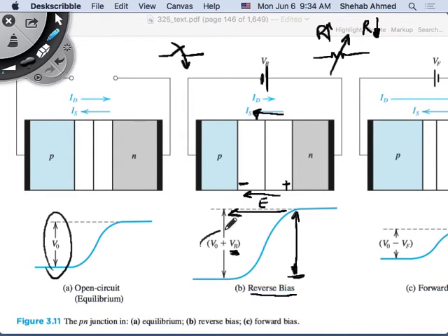Physically, what's happening is you are aiding or increasing the barrier voltage. What is the use for this? Here, we just said I'm creating a switch. I know it's a switch, but what is the use for it? Isn't a switch better because it's either 0 or 1? But with a mechanical switch, you need someone to sit down and push it. I cannot have 1 million people inside the processor.